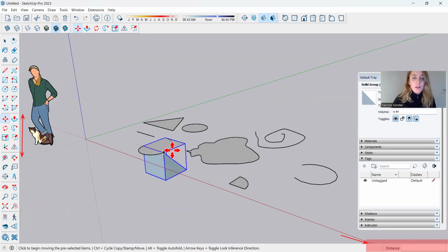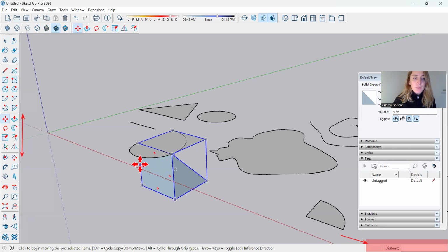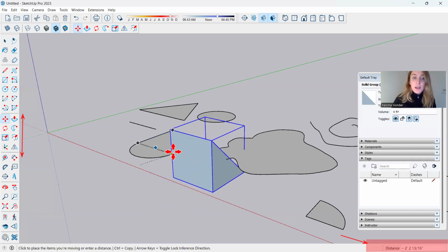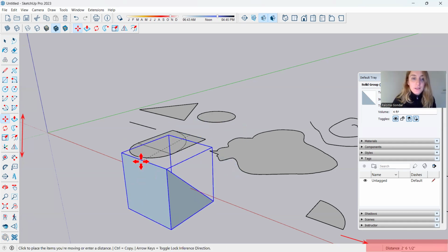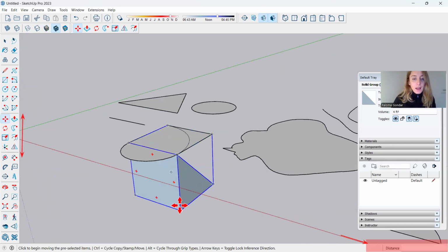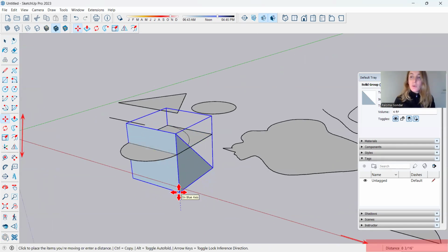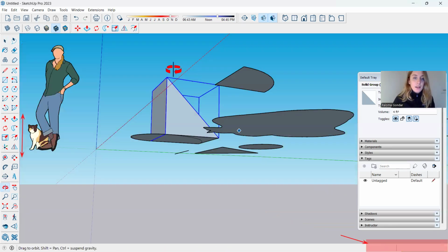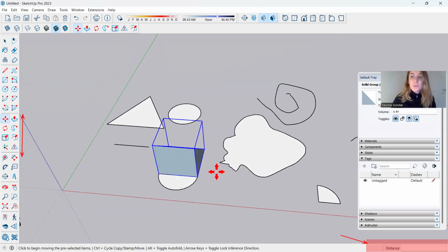So it sticks. So if I want, instead of from that point, from this midpoint, here's the midpoint of this group, I can move it to here. So here is the end point, and midpoint is exactly in the midpoint. And also always the program is showing us some signals. So from this midpoint, I can move it to that midpoint. And for example, I can move it up. So we need always to check the axis as well. So here it says on blue axis, and I can move it 2 feet up, for example, and I have it there. That is how we move.